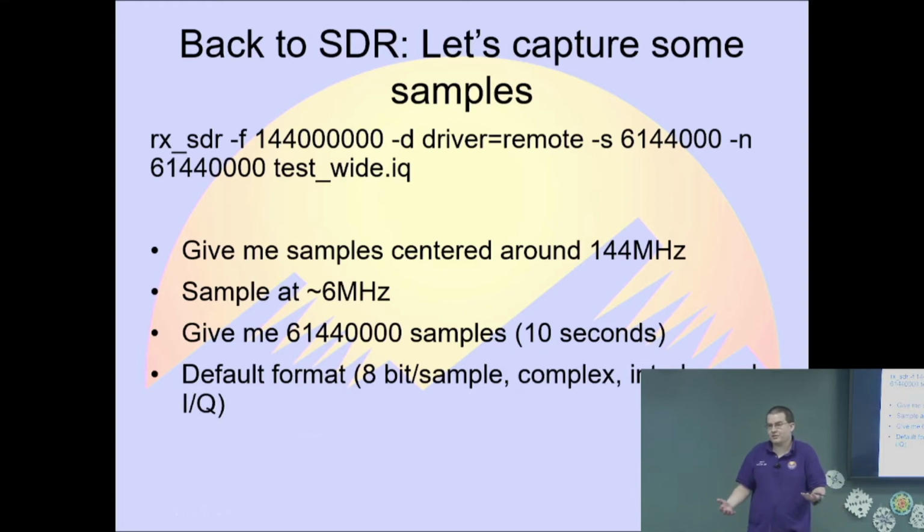And this is something that's really cool about SDRs. If you have a fast enough A to D, I can capture the entire 2 meter band. And if there's 2 or 3 nets going on at 6 p.m. on the weekday, I can listen to all 3 of them at once. And that's fantastic, right? But even more than that, I don't have to know what I want to listen to in advance. Maybe I don't know what signals there are, so get them all.